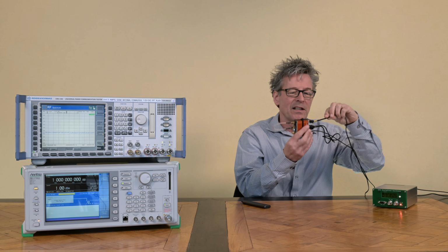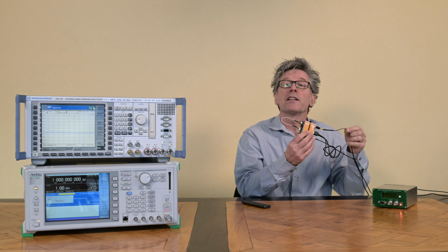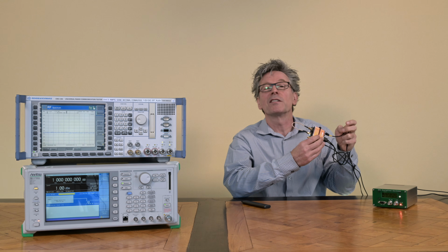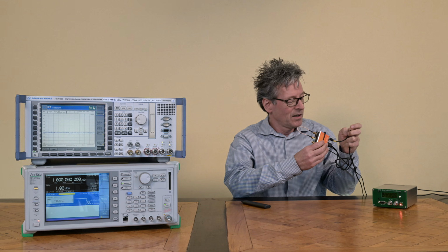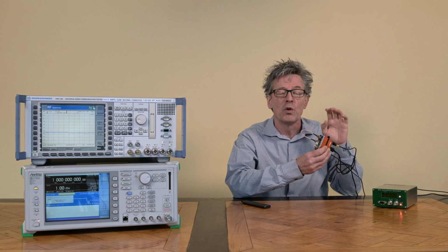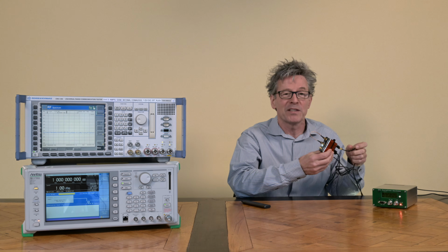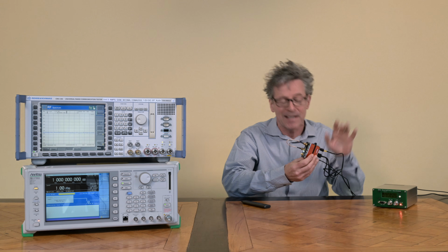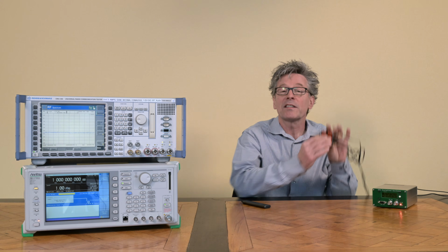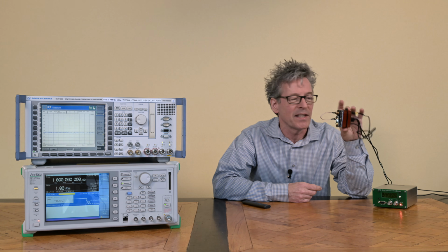I connected a DC power supply to the USB hub here. Funny enough, I had a whole bunch of old mobile phone power supplies that were rated at 5 volts. But actually when I measured them under a small load, they were producing like 8 or 9 volts. So let there be a warning. Always measure your power supply before you connect. I did that, happily enough. Otherwise I might have broken my new device here. So that's kind of the solution here. You might consider a similar type of thing.